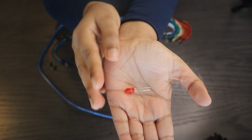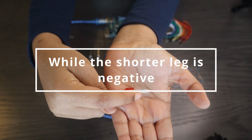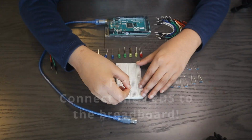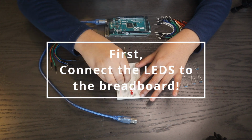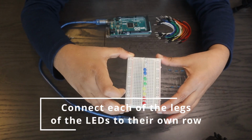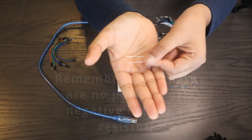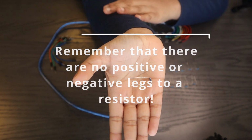This is an LED and the longer leg of an LED is positive while the shorter leg of the LED is negative. First, let's connect the LEDs to the breadboard. Connect each of the legs of the LEDs to their own rows like you see here. And remember, there are no negative or positive legs to a resistor.